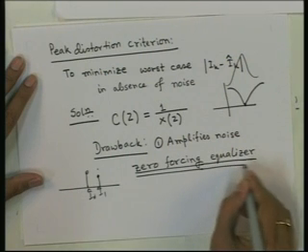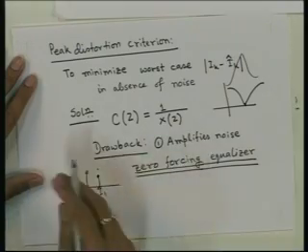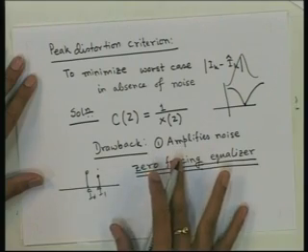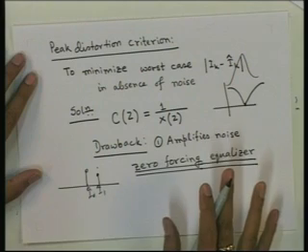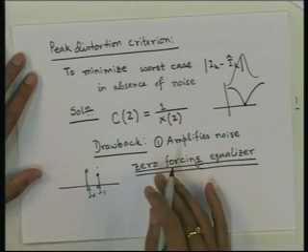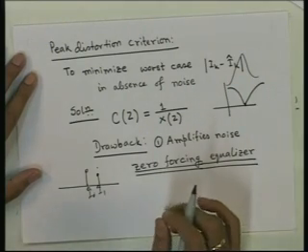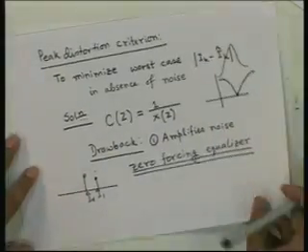which means that by this equalizer there is zero intersymbol interference. Okay. So, it completely eliminates interference between neighboring symbols, but it has the drawback that it amplifies noise in high attenuation frequencies, at the frequencies where the X(z) has high attenuation. Now, another criterion which is also very commonly used is the MSE criterion, that is the minimum mean square error criterion.